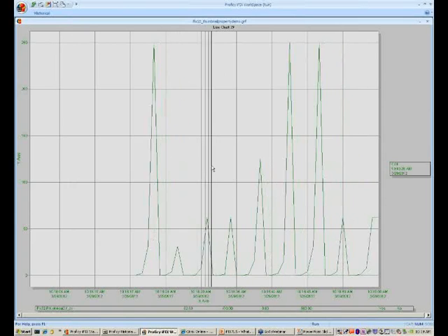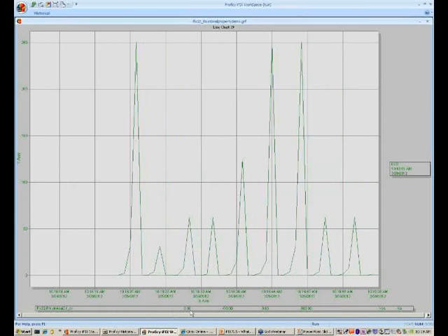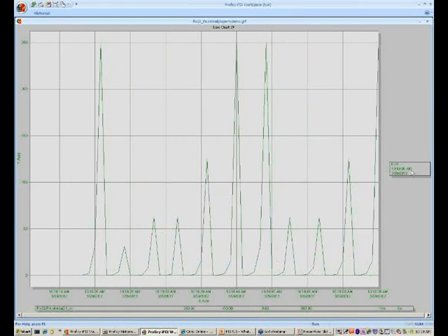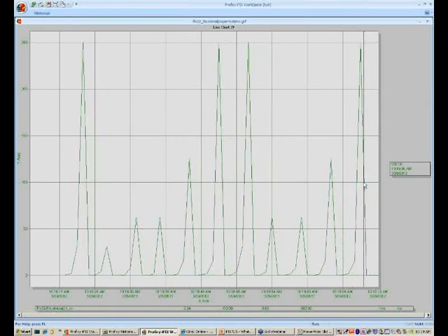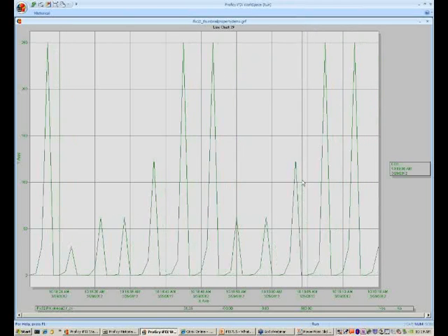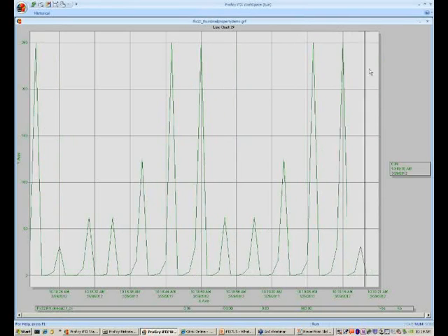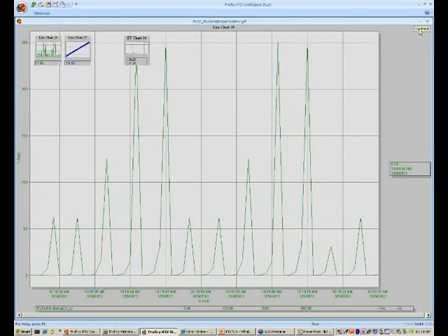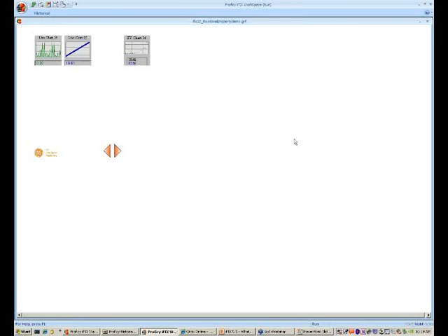So it takes that thumbnail mode and basically explodes it into a bigger view. And as it goes into the bigger view, it now shows you the entire legend of that particular pen that is being plotted. Or if you have a legend over here, it basically shows you. And this is one way you can display the tooltip. As you move the cursor here, it changes the value here. The other aspect is when in a full mode, again, when you move your mouse here, it comes up with a contract option, and then in runtime mode, you can go back to your thumbnail property. So an operator, while he is in runtime mode, can flip between a thumbnail and a regular chart object.